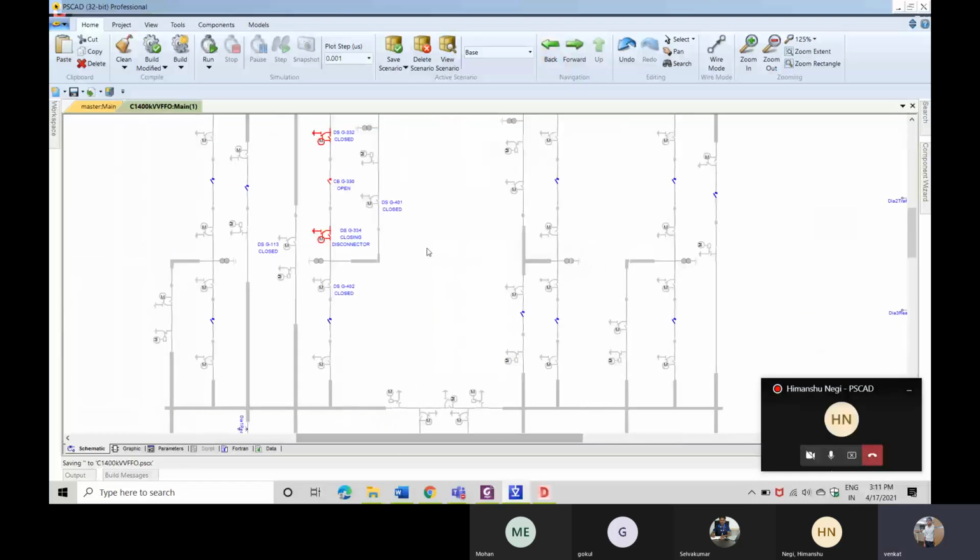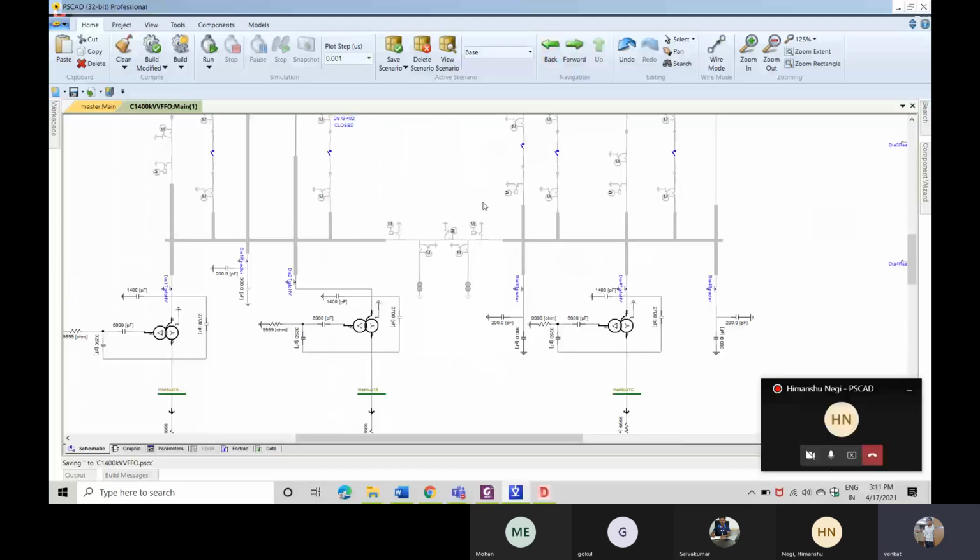Generally, the other information we have to get is how the 220 kV side modeling has been done. If the 220 kV side has any transmission line, then there also we have to study this lightning impact. I hope that is clear. Yes, I got it. We have to model that, perform a lightning study there, and see how this impacts the insulation strength of the substation. Exactly, that we have to see.